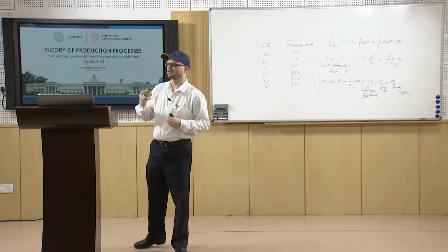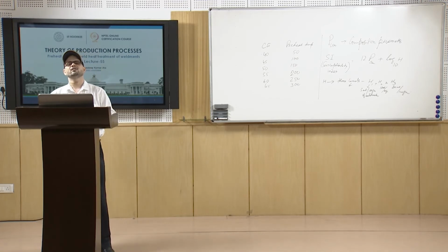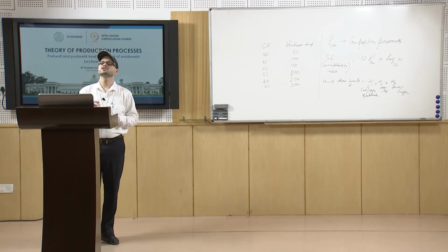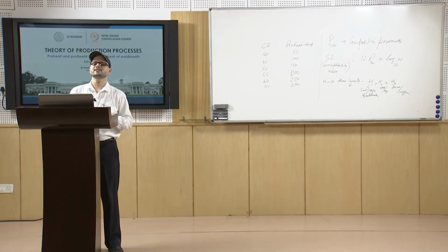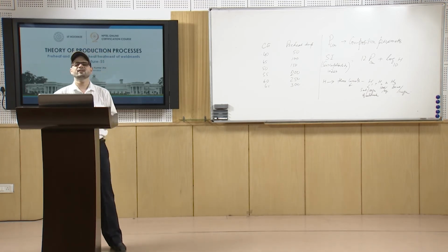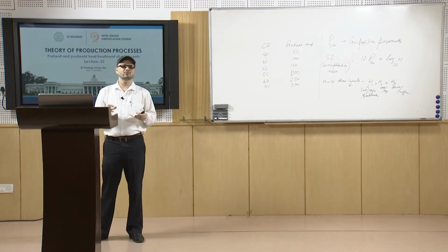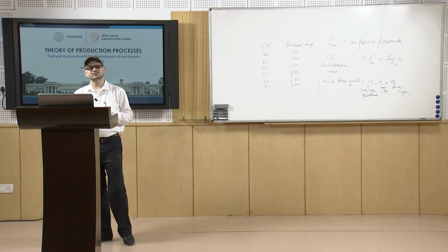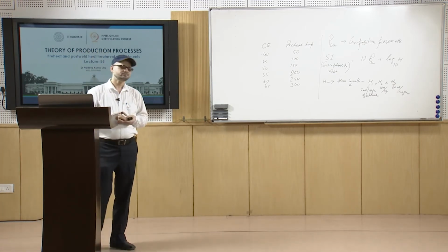So, that is another requirement in the case of stainless steel, where preheating of 100 to 300 degrees C is used. Normally, for thickness of less than 10 mm, and when the chromium percentage is about 13% and carbon 0.1 to 0.12%, there is no requirement of preheat in those cases.